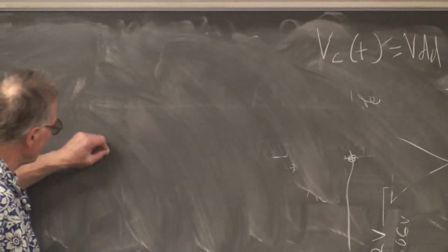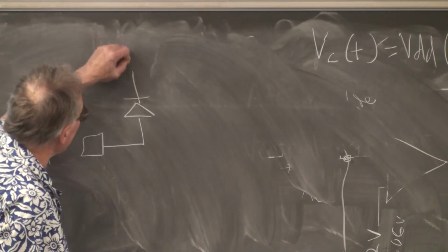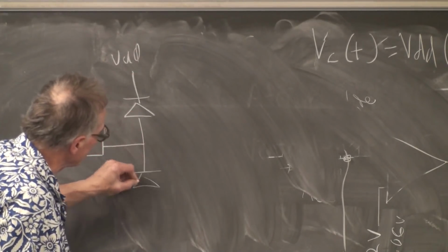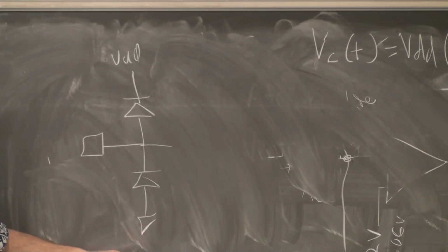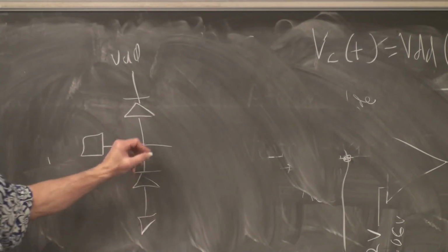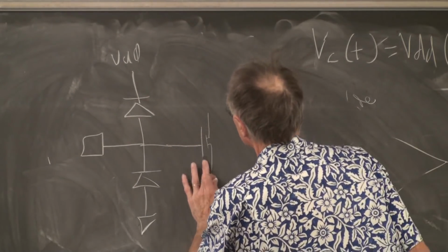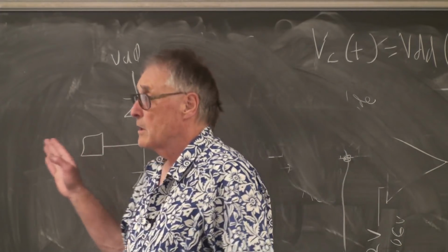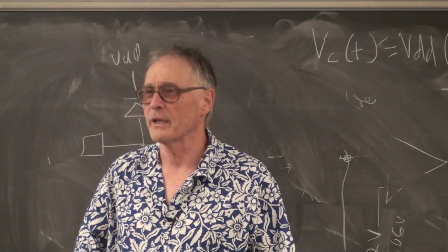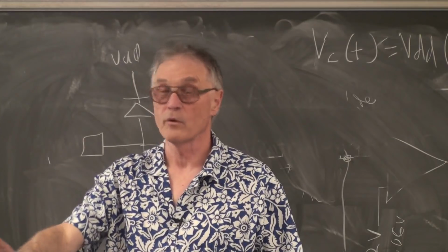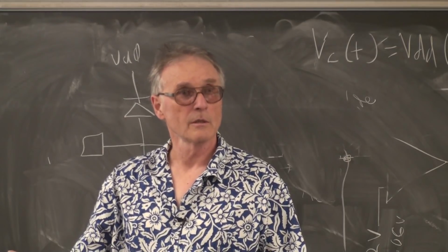if you look at the details of an input pin, it has a Schottky clamp diode up to VDD and another Schottky clamp diode down to ground, so that the voltage can't go much above VDD or much below ground. And then the input of this thing really is just a CMOS gate, right? That's horrible. And you can turn on an input, particularly one of the analog inputs where you can actually measure voltage. Turn on an analog input, don't connect it to anything, move your hand back and forth, and you can change the voltage on the pin. Oh, that sounds like a capacitance switch. And it is, in fact.